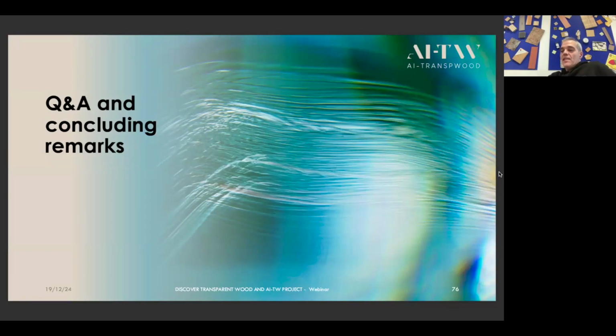Do not forget also that, as you heard during the presentations, apart from the possibility of using some biosourced infiltration resins or resins having a quite high bio-based carbon content nowadays, the best and very well optimized resin systems for transparent wood are mostly acrylates. You need to move from fossil-derived acrylates to something that is more sustainable.